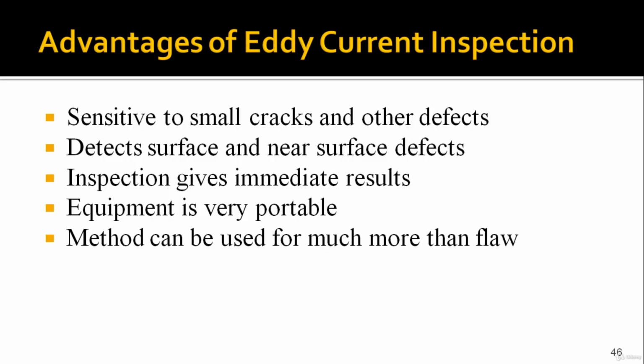The method can be used for much more than flaws. Like other methods, you can only find flaws and defects. But in eddy current testing you can do conductivity measurement, thickness measurement, and corrosion layer thickness measurement. So apart from this, there are lots of uses of eddy current testing. That's why it is very important in industries.